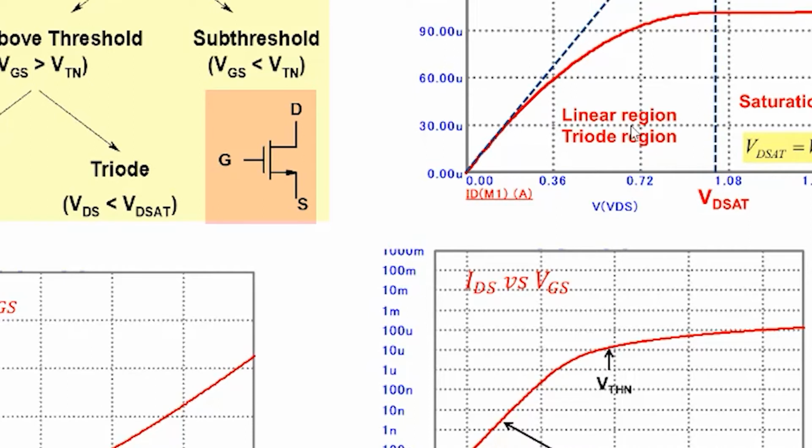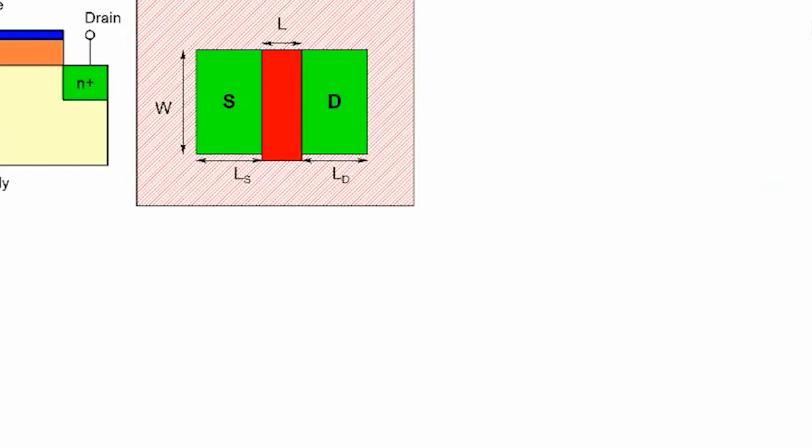So for amplifiers, most of the time our transistor will be biased above threshold. For constructing amplifiers, we want to be in this region. If you recall the discussion related to amplifiers, we wanted output characteristics to be flat like this. And so we want to bias a transistor in this particular region. So let's look at the DC.